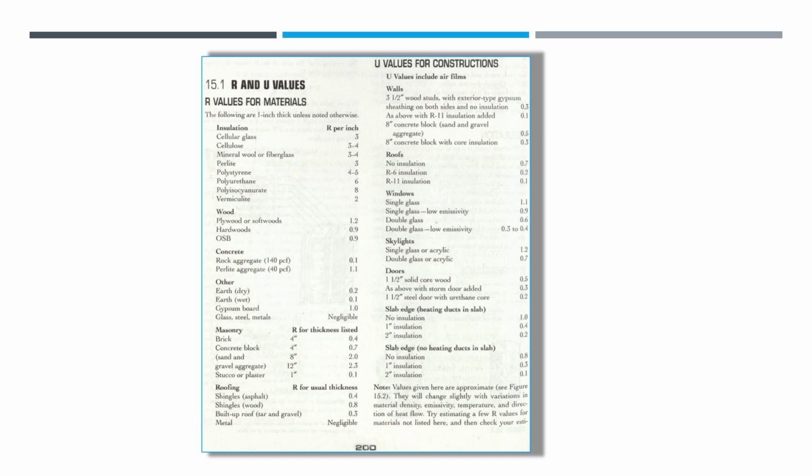So we should have already talked about R and U values. Dr. Kosak, in this last lecture that he posted, did a really good job explaining what this table was, and it's in your book, obviously page 200. In the PowerPoint there were a couple of images of some cross sections with different layers in them, and those are the different R values for the insulation, the resistance. And later we're going to be calculating what the temperature of one specific layer would be depending on the temperatures on the outside and the inside and the other R values we have.